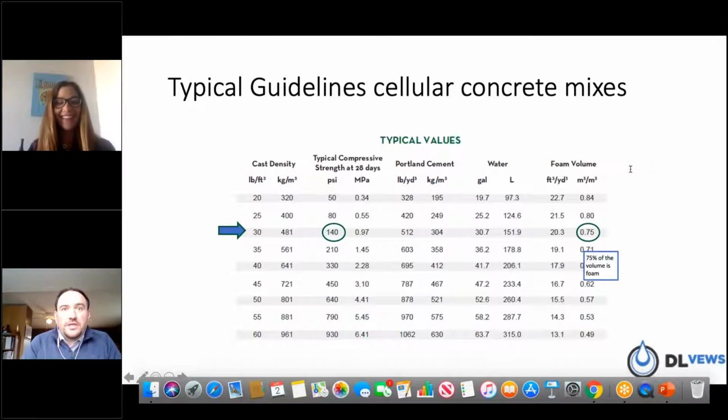Absolutely. So the question is, in the presence of water in an annulus space or voids, is cellular concrete a good idea to utilize? It's a bit of a loaded question, but a great one. A couple of things should be considered. Is that stagnant water? Is it water where you just had a 5-day rain event and you've got water gushing into that host pipe while you're trying to line it? Is it coming in above you, overhead, in a larger culvert? You've got the presence of groundwater just seeping in at your 12 o'clock or what have you. These are all good things to consider.